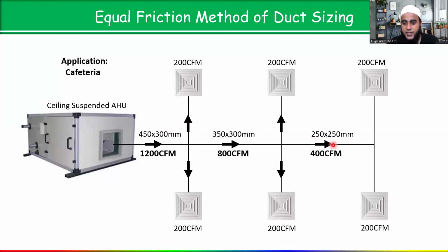But here, when you see, we have reduced the height also. In this case, in the main duct it is 250. So what is better? In the branch duct, better is to maintain 200 mm height. Always less than whatever height you are maintaining in the main duct. Okay, so let's see now. Simple. Here I have opened the duct sizer software.